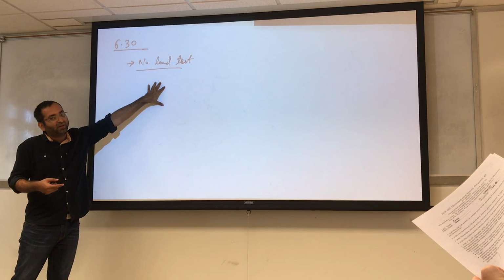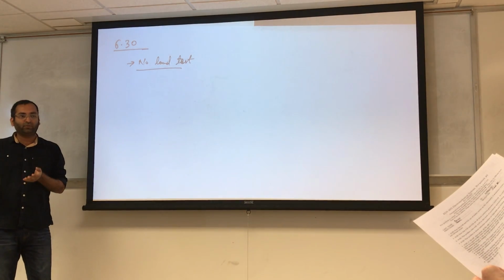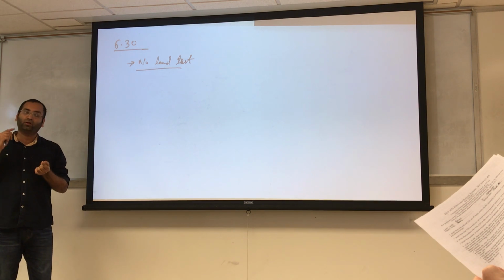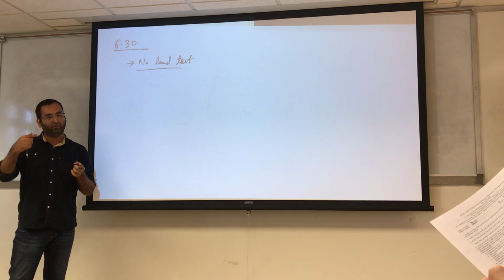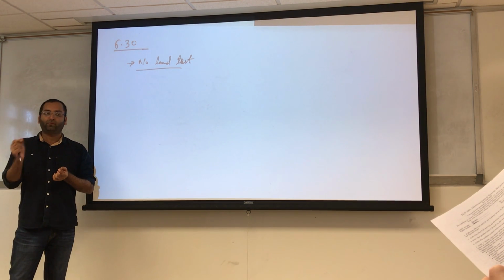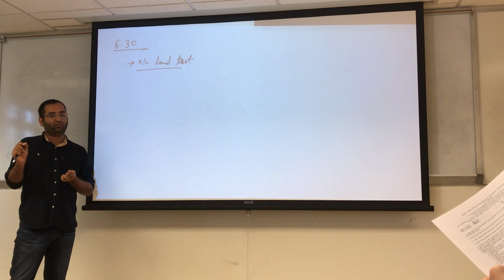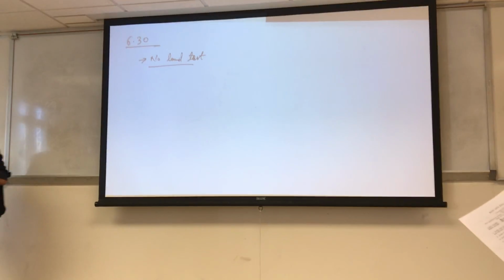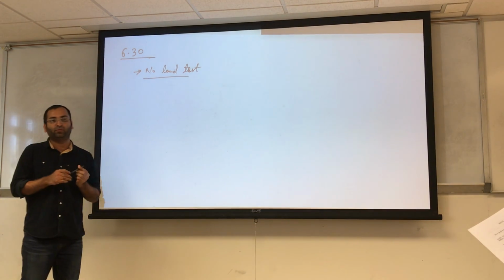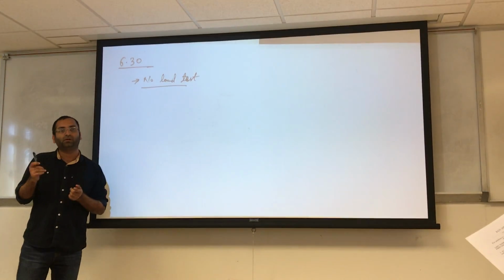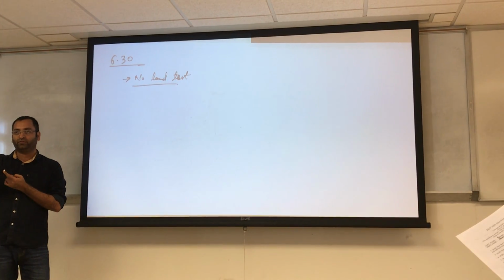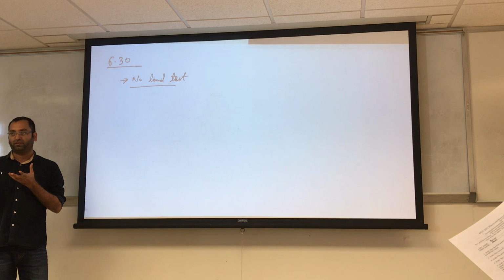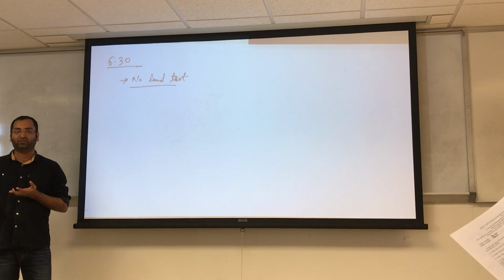In an induction motor, it can't be zero. It will never be zero. It will always have some inertia. So it will always be more than zero, but very close to zero. Free rotation means the maximum speed, and the slip should be very close to zero. It will not be exactly equal to zero. Because if you remember the demo on YouTube, when the speed of the rotor is equal to the speed of the stator, then there is a lock. That means it will run as a synchronous machine. It will not be an induction machine anymore.